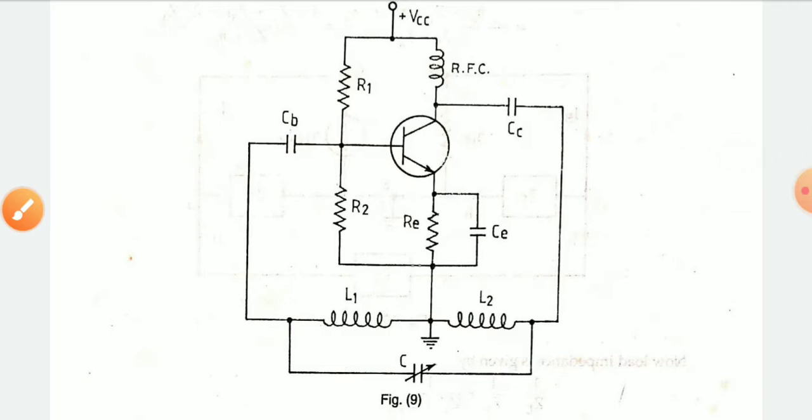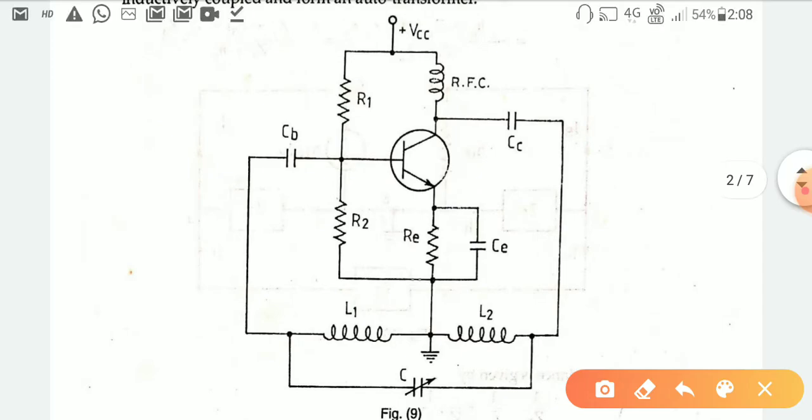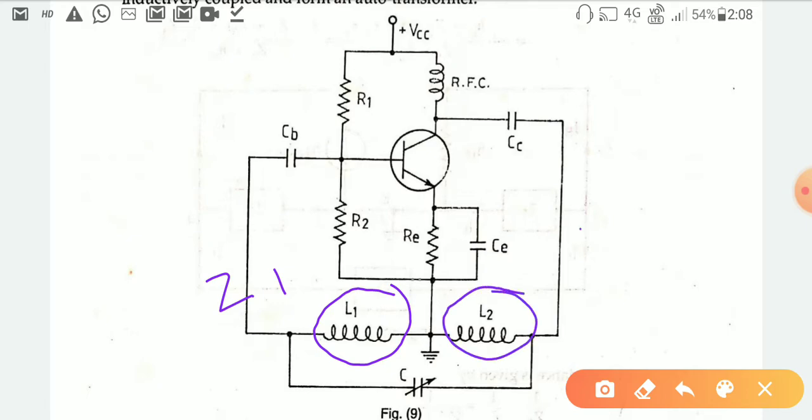So we are going to the equivalent circuit diagram for this total configuration. For the equivalent circuit diagram, we introduce L1 as the impedance Z1, L2 is replaced as Z2, and C is replaced as Z3.